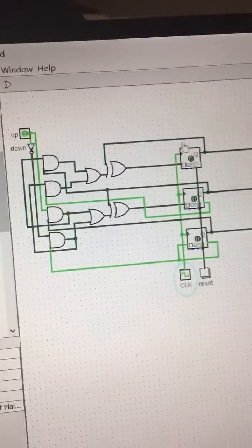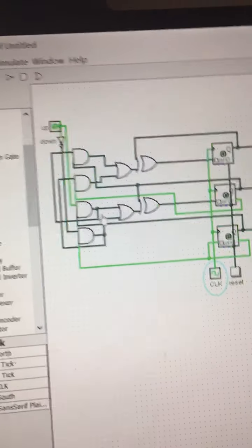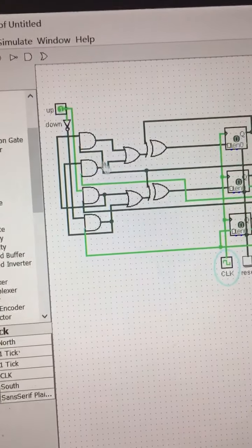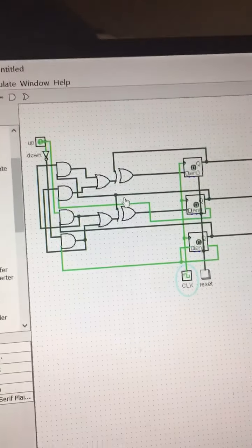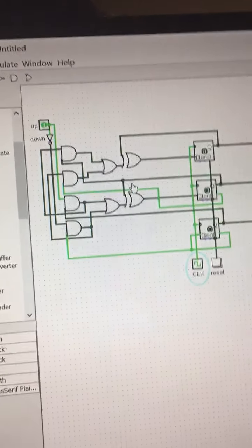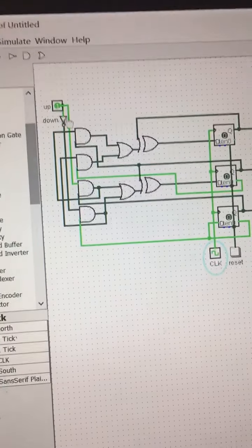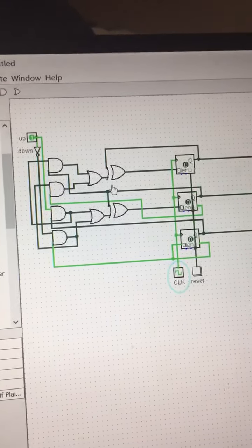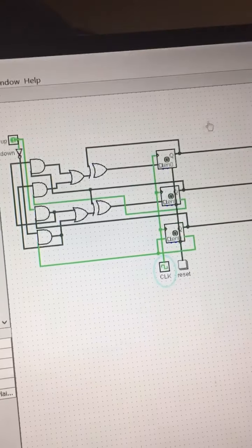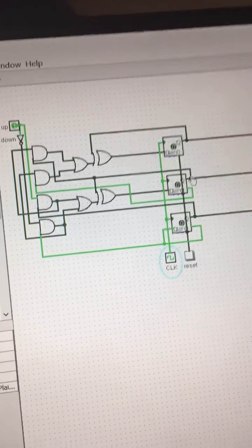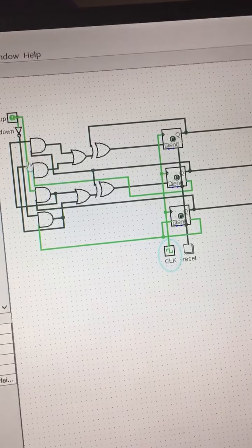So similarly for the third digit as well, but instead of just connecting the up and down with the AND gates, you actually connect the previous results of the AND gates to the AND gates here. Because remember, when you're trying to change the third digit, both of the previous two digits have to carry or borrow. So you just literally use what's before, right? The AND from before, and then connect these to these, so that you make sure that all of the things previously are borrowing or carrying. And then you AND these with the complement or the actual output into these AND gates.